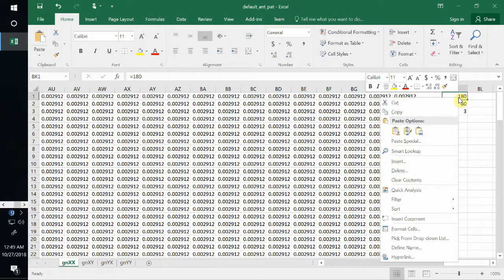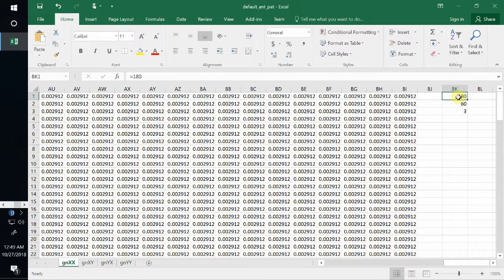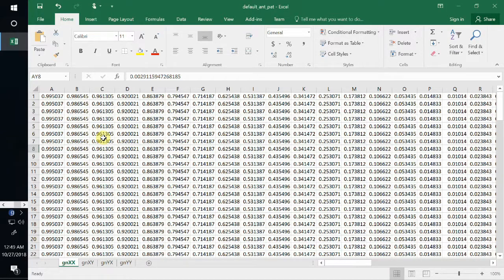The same can be done about the values going down the column axis, which represent the phi values, in which case you are doubling everything. You have 360, 120 as your number of points, and again, when you divide those values over each other, you get 36 over 12 is equal to 3 degrees of resolution again. So you could imagine it's a surface map of the antenna pattern, or the normalized voltage antenna pattern. As you can see, nothing exceeds 1 inside this spreadsheet.